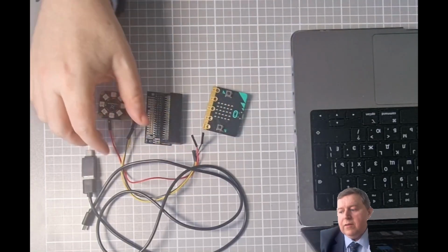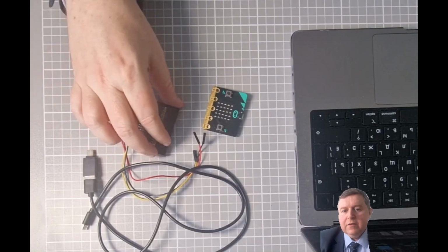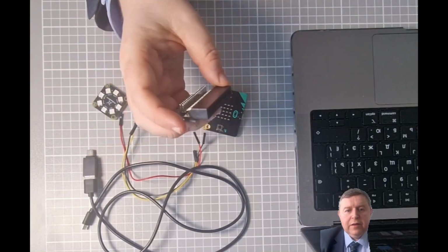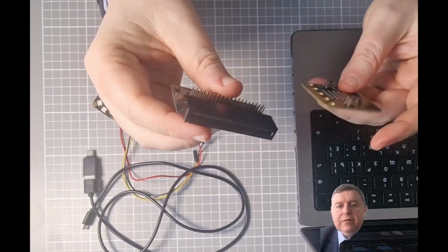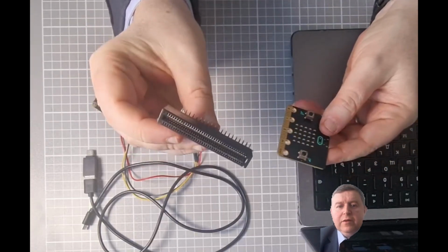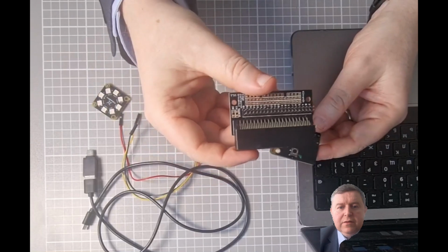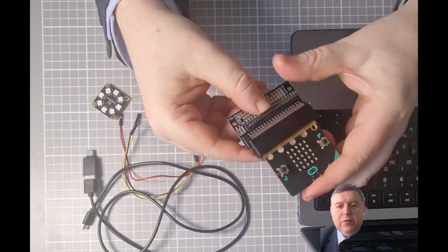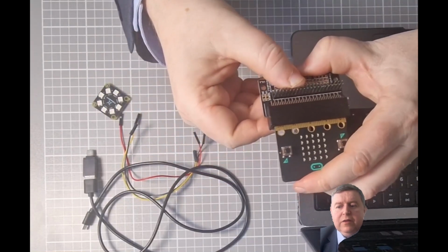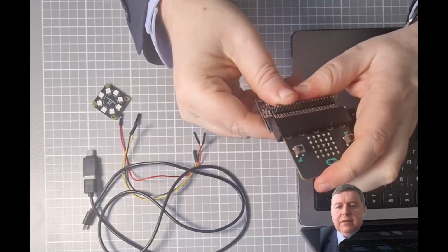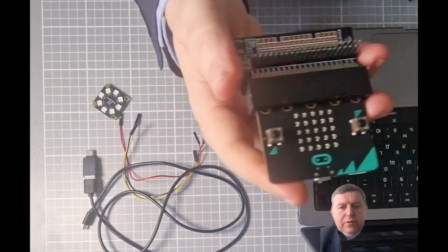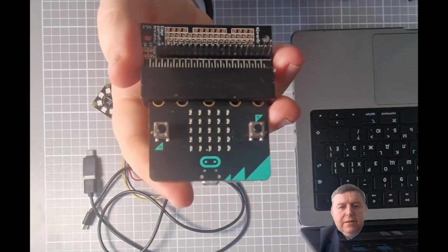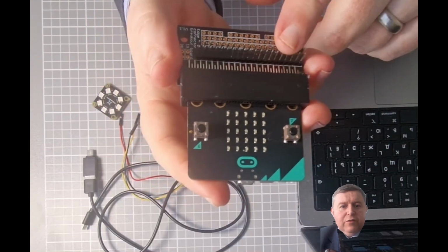And the 3 cables here. Okay, so first thing we're going to do is take our breakout board and connect it. Make sure it's connected the right direction, so it should face up like this, and then the microbit should go in like that, and it should snap together like so. It takes a bit of force, so it should look like this when you're finished. The button should be on the top, and the pin should also be on the top here.